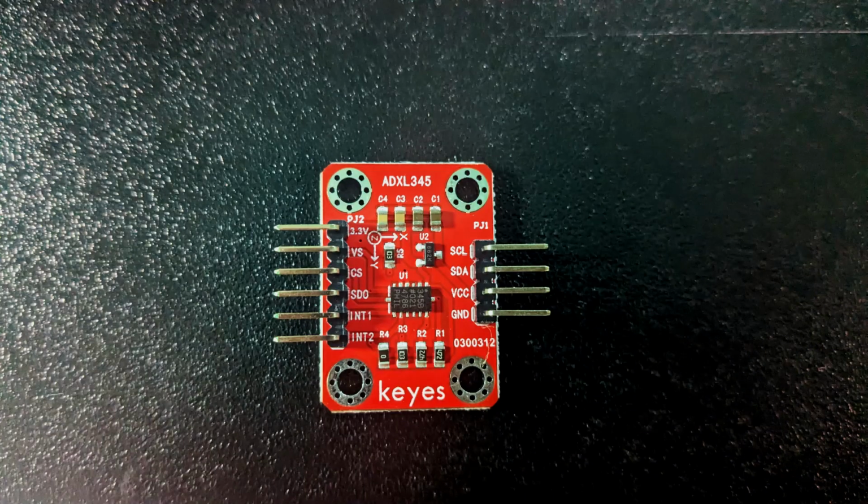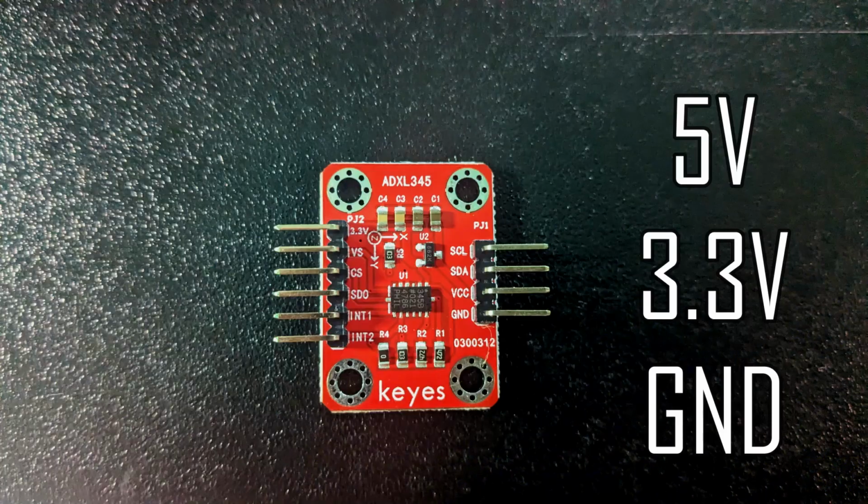The one I'm using today is the ADXL345. It can work with either SPI or I2C communication. It has 10 pins, but not all of them have to be used. The pins are VCC, which connects to a 5-volt power source, 3.3V, which connects to the 3.3-volt power source, ground,